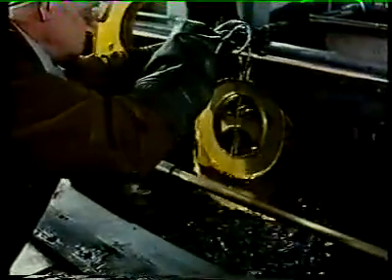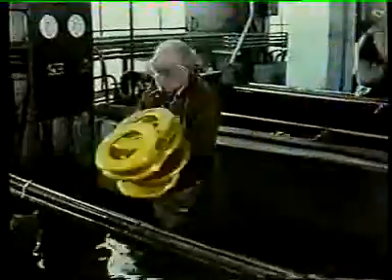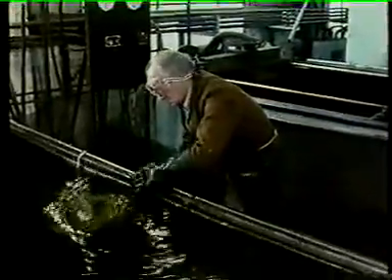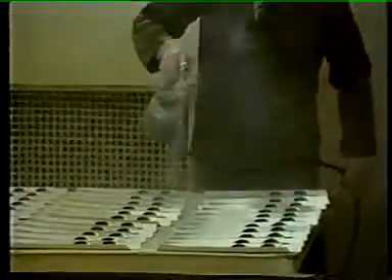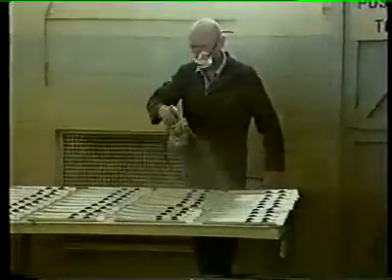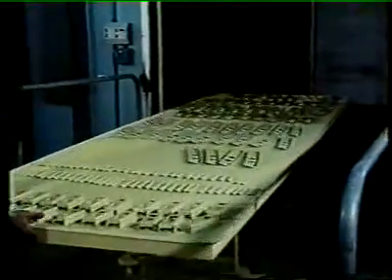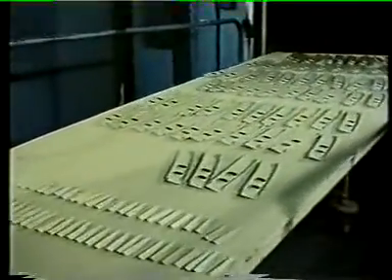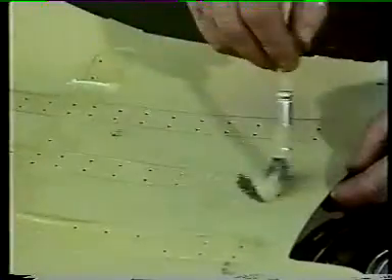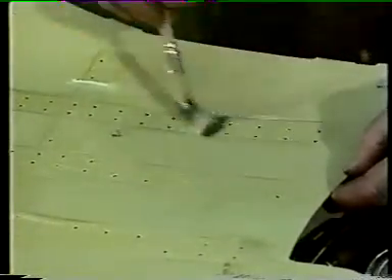All components and sub-assemblies are pre-treated and primed all over, not just on outer surfaces. The primer contains a corrosion inhibitor, and the finish protects the primer. In order to ensure there is no contact between metals and to prevent fluids getting in, wet jointing compounds are used during assembly. All wet assembly materials are corrosion inhibited. Crevices and depressions must be filled with sealant.